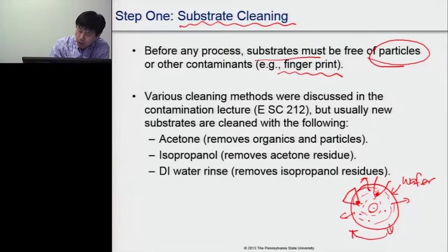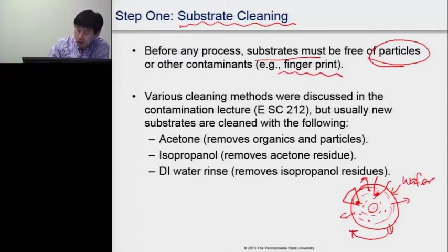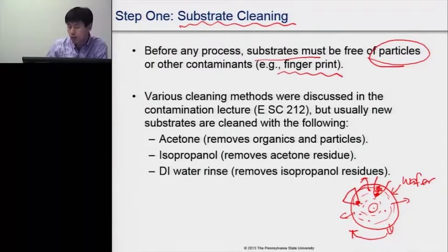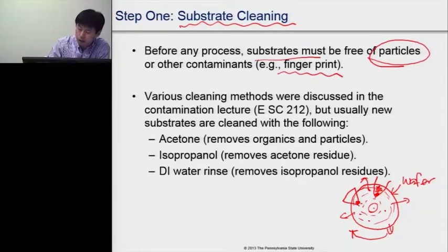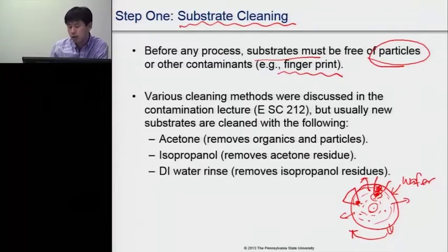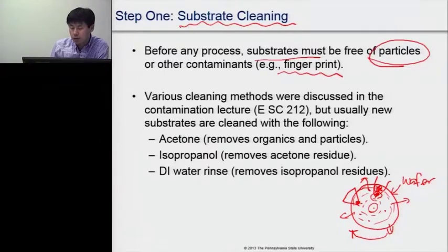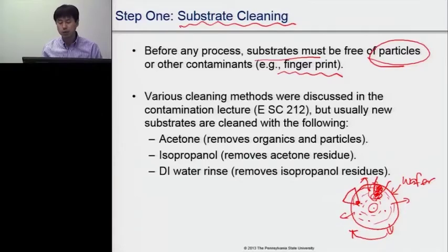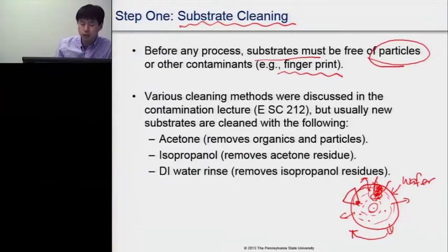The particle blocks the uniform spread of the photosensitive layer, and inside this conical shape the thickness of the resist is much thinner. So this area, and the area the particle is sitting on, the patterns might be damaged and will not be properly transferred.